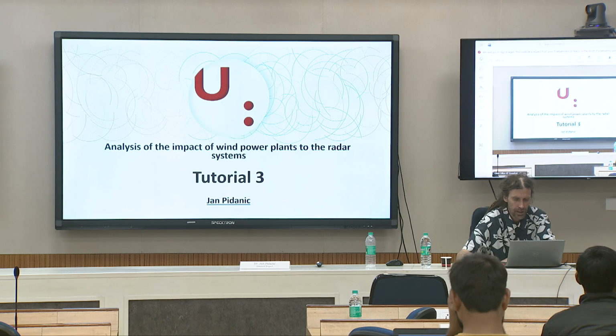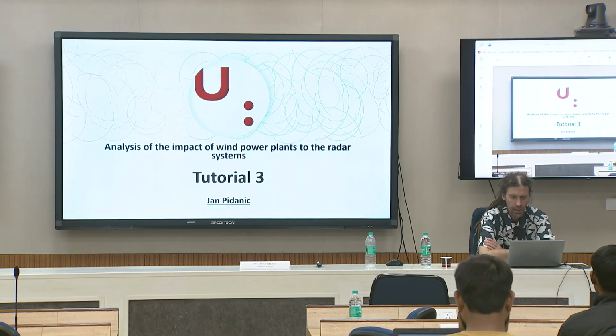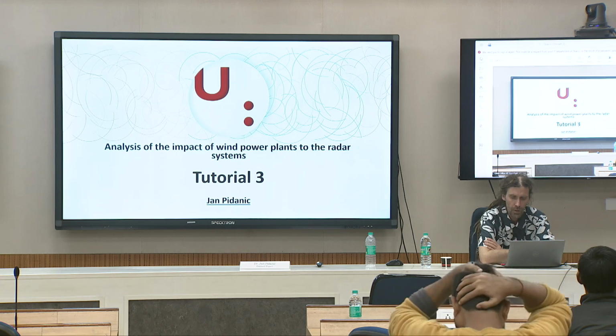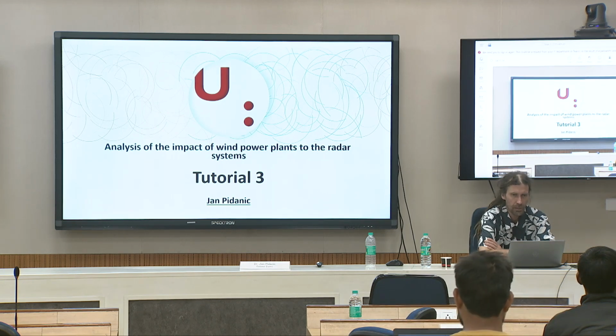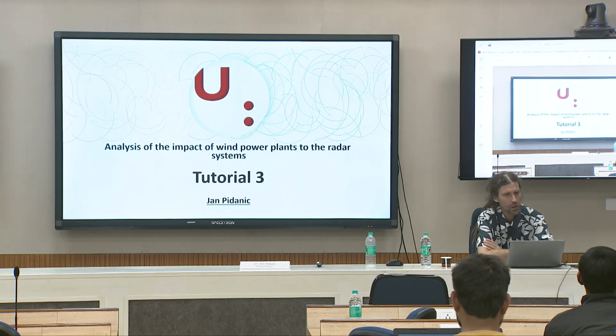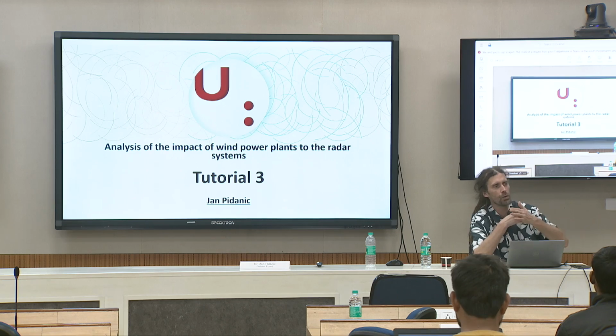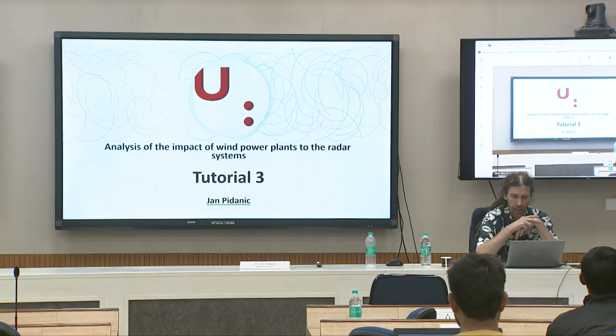The third layer is geospatial, and it is related to how we use tools like OpenStreetMap, Google Maps, Maps.com, QGIS software, together with digital elevation models for getting information before measurement, like line of sight and clutter. It means clutter like buildings, barns, woods, mountains, and anything that could matter during the planning of the measurement. And of course the visibility of specific turbines.